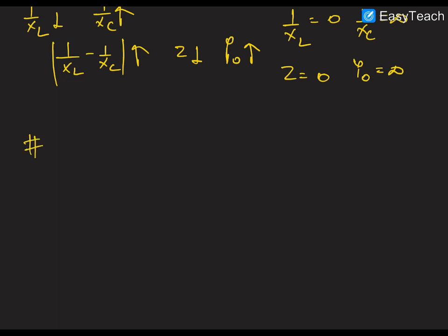Like we use series LCR in radio receiving, if we had used a parallel LCR instead, then at the resonance frequency the impedance of the circuit will become maximum, and the circuit will not allow that frequency to get mixed into the current, and therefore the circuit will behave like a rejector circuit.